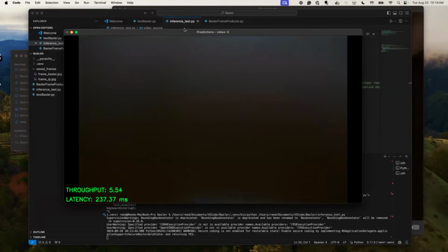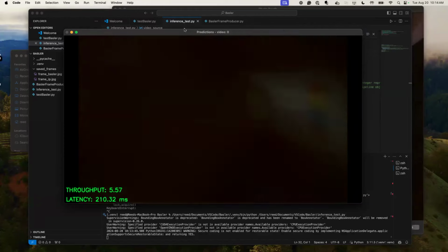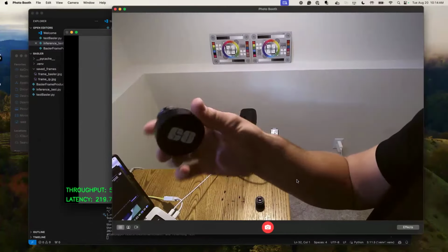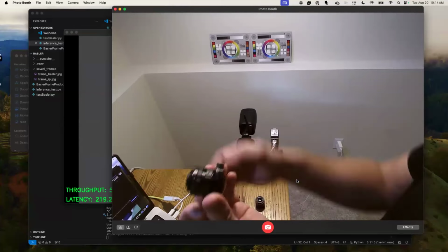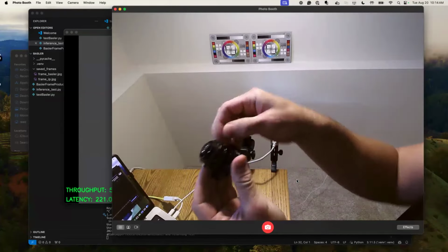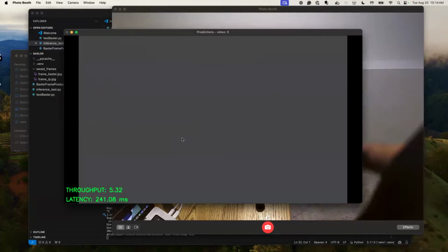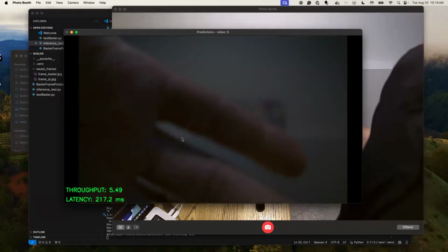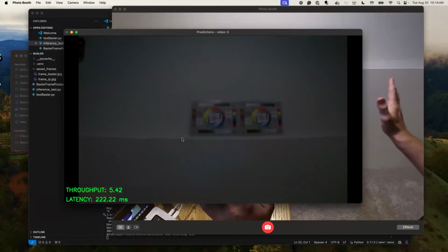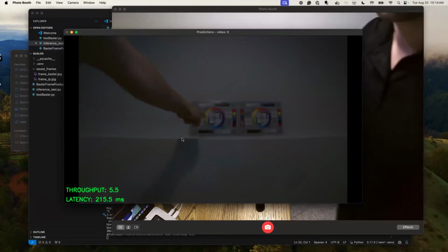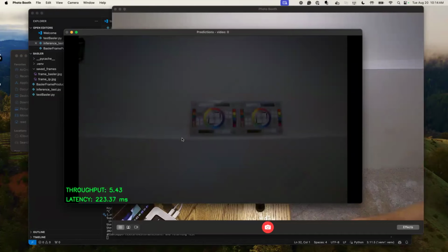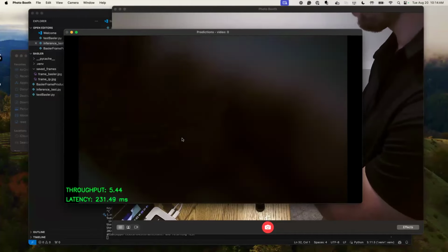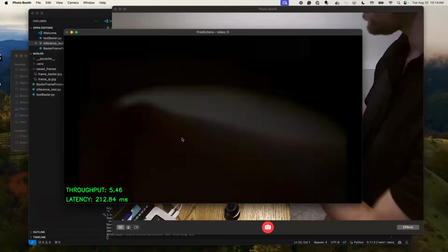What I mentioned is we can actually swap out lenses. This is a good lens for this application, but what if I wanted a lens that gives me a wider field of view, such as this one? On these, there are two different knobs. One opens the aperture, which is how much brightness you're letting in. The other is focus, so you can get a crisp image of your application. I'm going to put this on, and we can see how the field of view changes with the simple lens swap. It's way more zoomed out. If my goal is to detect this target, I would not want this lens, but with a simple swap of a lens, you can get a very different field of view. I'm going to take that off and put my other lens back on.